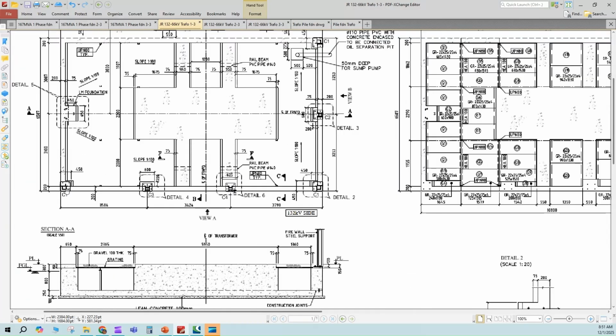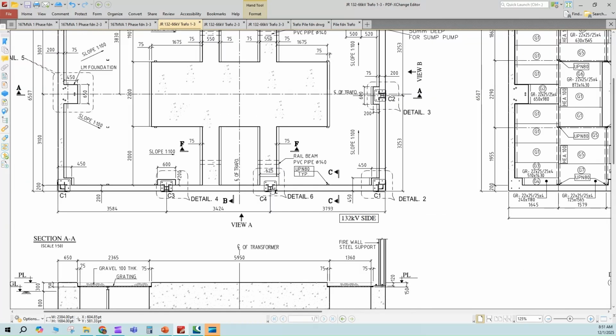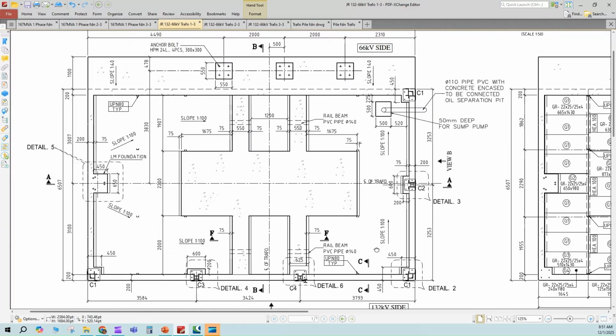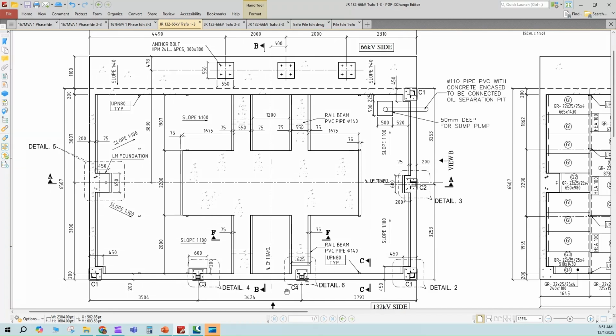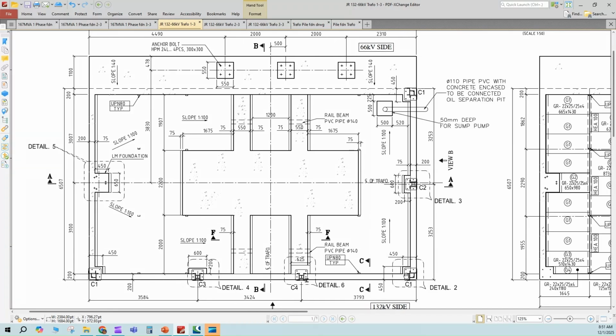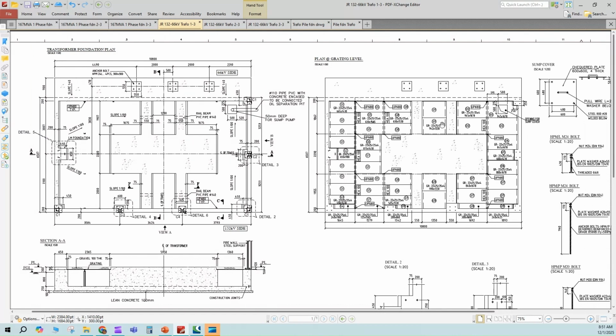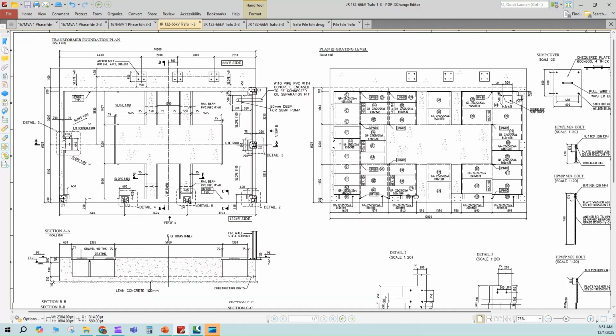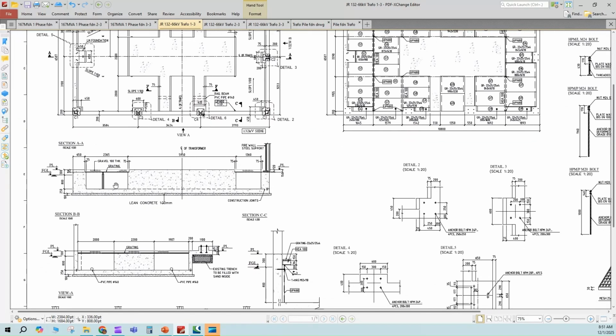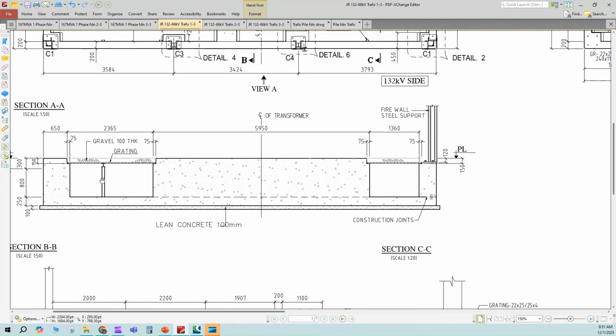So these are the structural mountings over the transformer bund wall. This structure is to hold the precast concrete element for firewall protection. And these are accessories. This is equipment support, detail 5. And the grating should be segregated like this. Each individual panel is to be mounted on the supports like this.